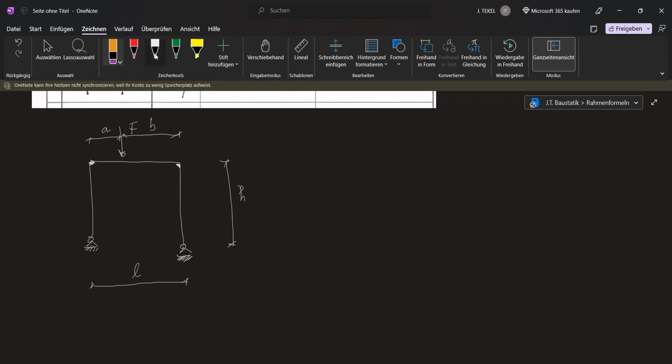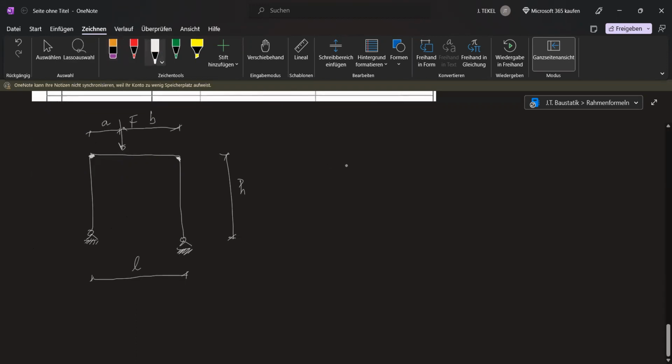So let's get moving. I'm gonna use the same statically determinate system that we used in the previous calculation. So I'm basically gonna remove the horizontal load on the right pin support, turning it into a roller support. So in the, let's call it 0 load case, we're gonna have the chosen statically determinate system with the external load, the force F acting on it.